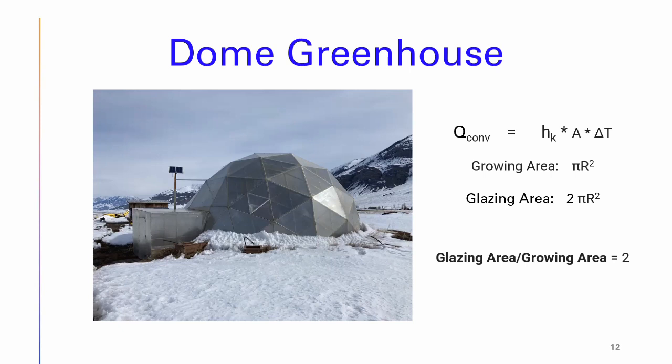And then because of the curved surface, polyiso is fairly rigid. But if you get unfaced, because normally there's a felt that goes on your polyiso, if you get 1 inch or ½ inch polyiso that's unfaced, it'll bend to match the curvature of my kits. The other thing you could do is use polystyrene. Polystyrene is a very poor insulator.